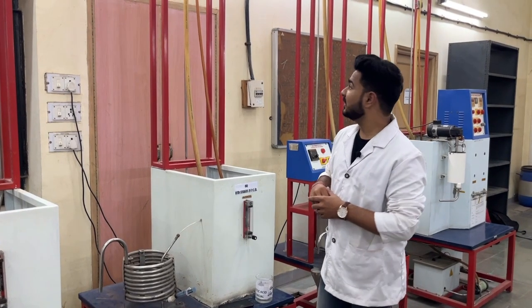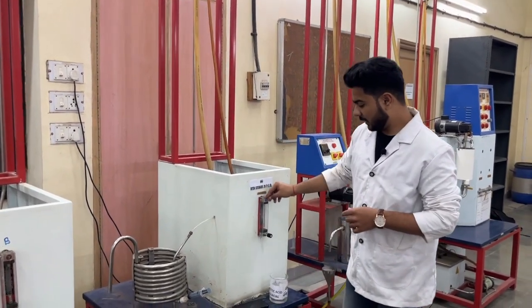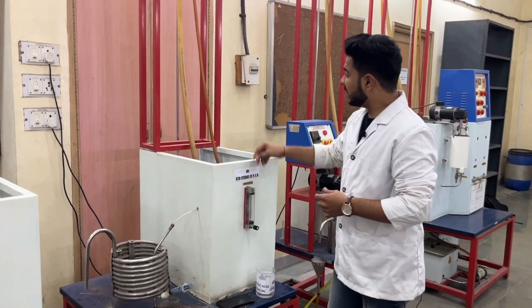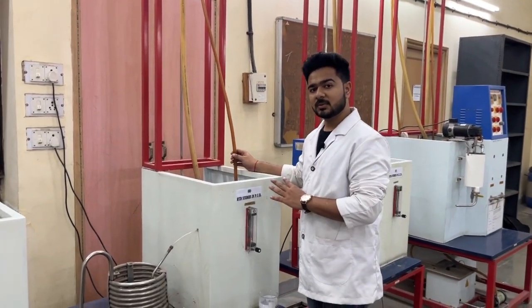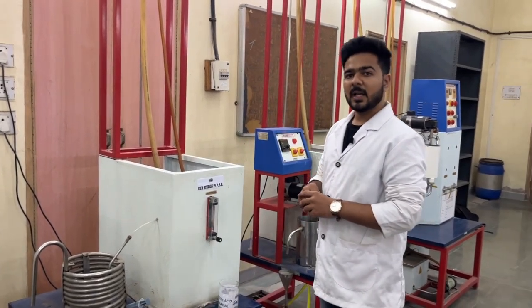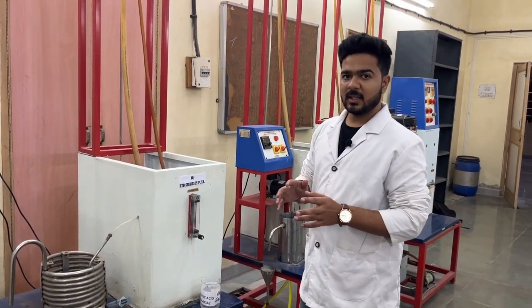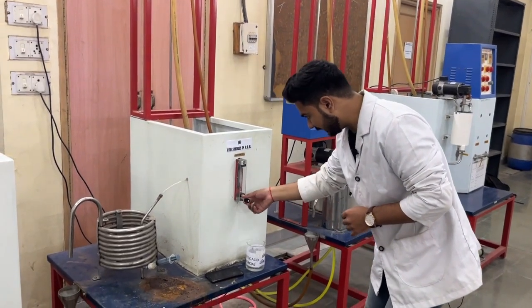Now we will notice that the liquid has started flowing from the overhead tank to the rotameter valve. We will make sure that there are no air packets in this pipe so that smooth recirculation is maintained. Then for our first reading, we would like to maintain the flow rate at 10 liters per hour. So we will turn on our rotameter valve and set it to 10 liters per hour.